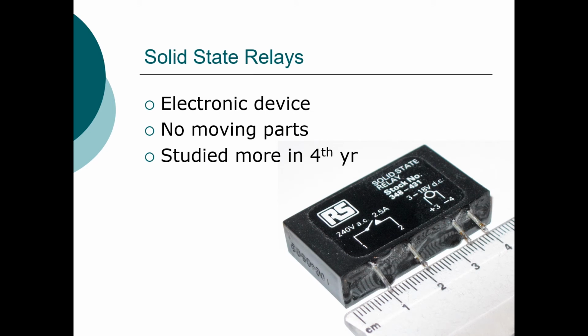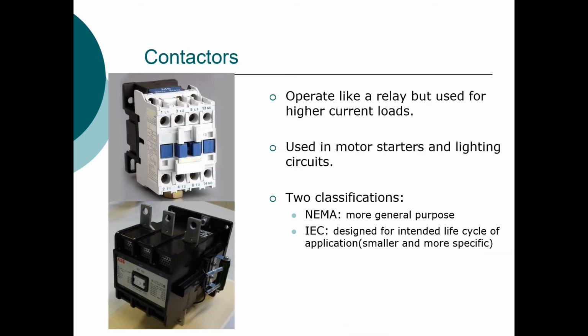Most of the electronics that we have in our house and in our businesses use solid state relays. These electronic devices don't have any moving parts, and you'll look at these more in 4th year. For higher power loads that would require more frequent operations, we can use a contactor. They operate like a relay, but they can operate higher current loads.